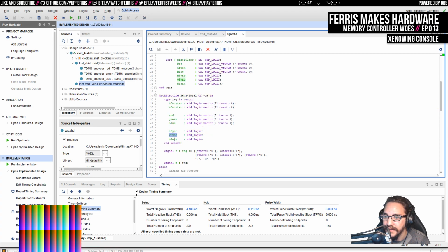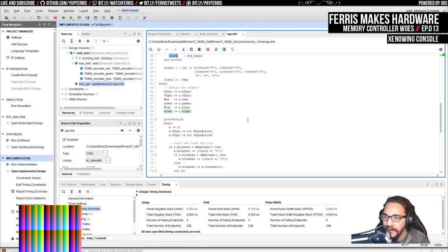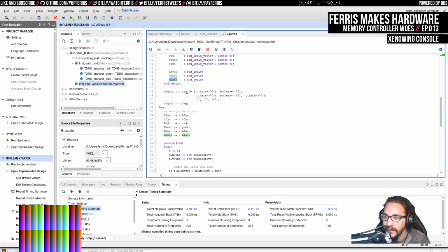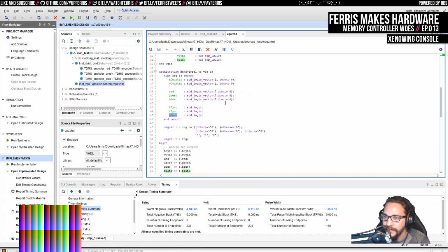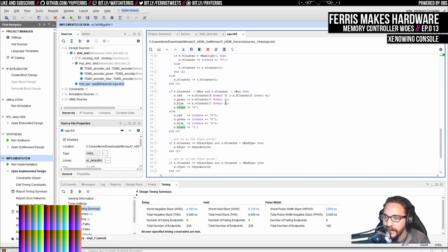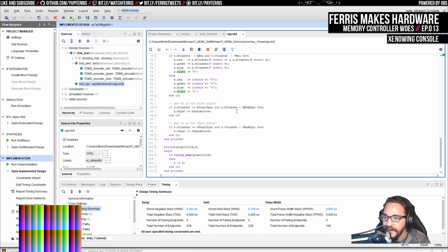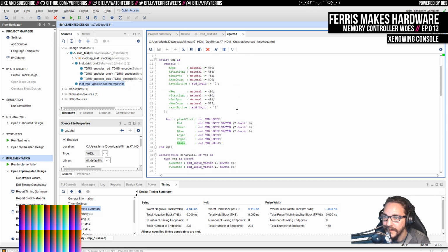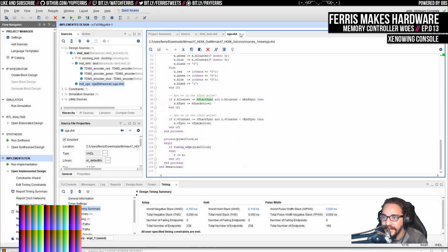We have H-sync, V-sync, and blank. Sign the outputs. What's R? Is this register here? Looks like it just collects all this. There we go. That's where that's set. Yeah, so that's pretty basic output of this, and then these are all the different timings. So here's the resolution, when the sync signal starts, when it ends, the max count here. Nice thing about generating VGA is you can just look at these very basic counts, and you can find tables for these all over the place. So that's nice. That's the one I expect to be really straightforward.